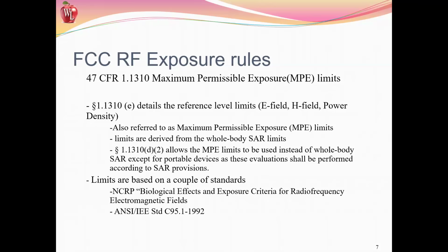Portable devices, you're looking more, they're closer to the body, so therefore you have to actually do the tests. And the limits come out of a couple basic standards, the biological effects and exposure criteria of radio frequency electromagnetic fields from the NCRP. And ANSI has a standard C95.1 that has this information.